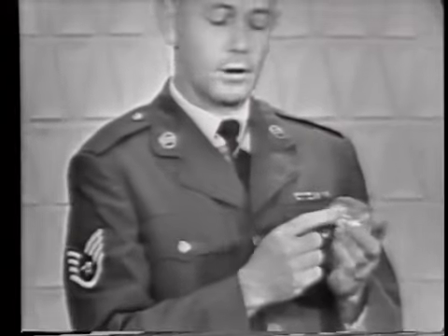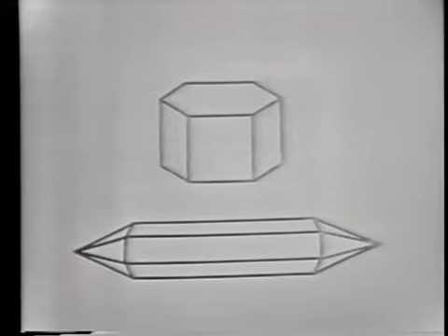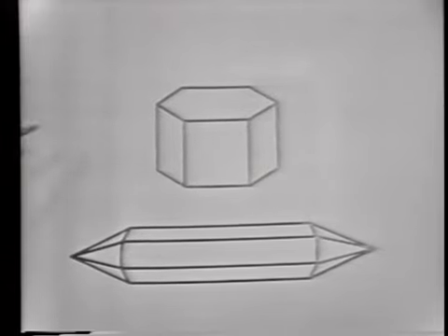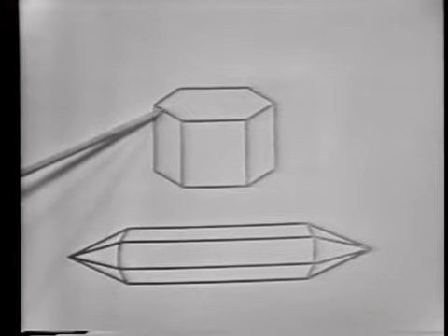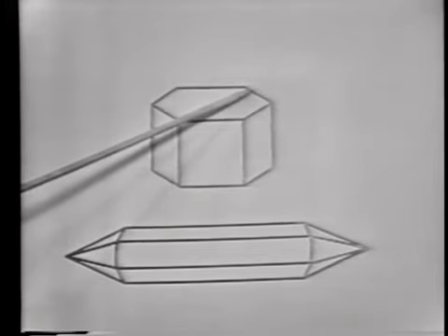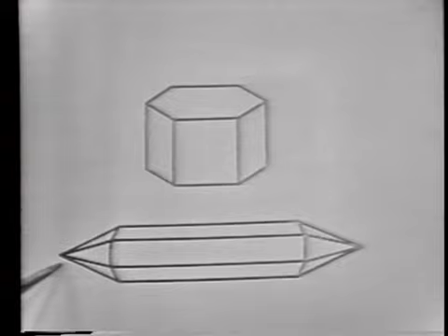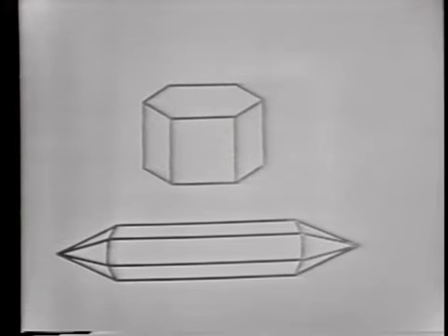Now, let's take a look at this drawing so that we can determine more about the quartz crystal. There are 2 views. The top view indeed shows us that the quartz crystal has a hexagon shape, 6 sides. While the lower view points out that indeed the quartz crystal in its natural form does have pointed ends. Quartz crystal in its natural form cannot possibly be used in oscillator circuits. It must be cut in a specific manner to exhibit its piezoelectric properties.